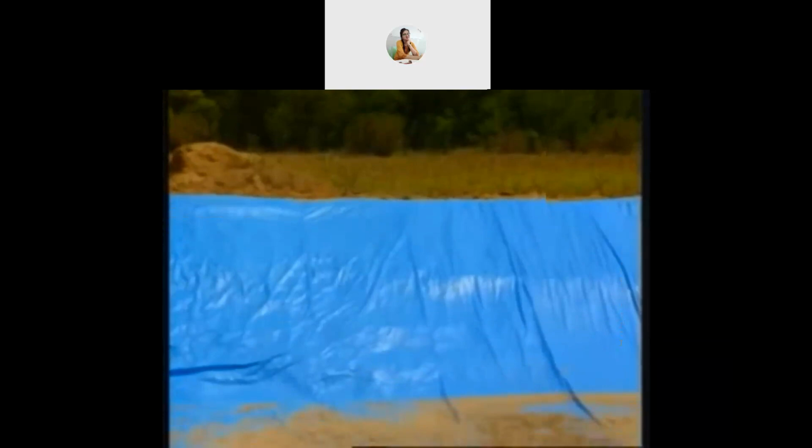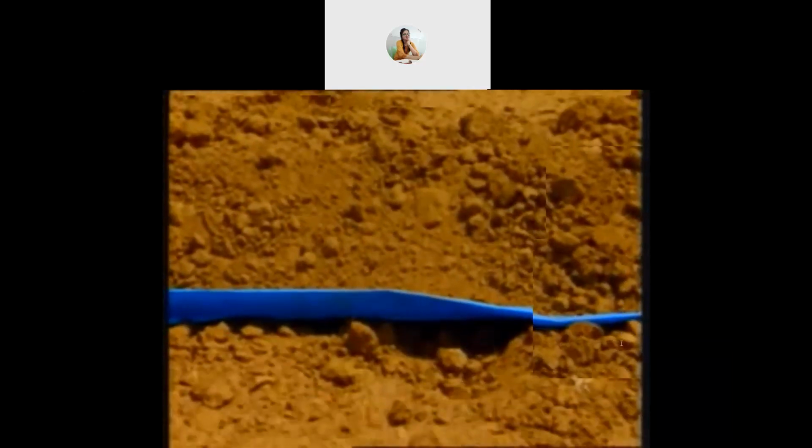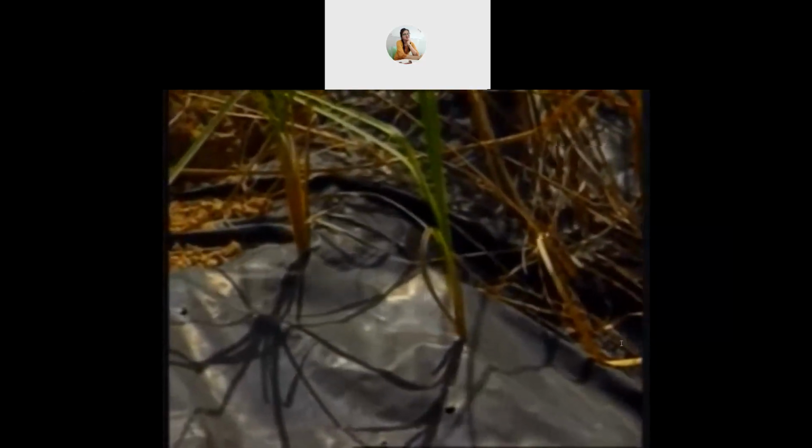Plastic film and a layer of bentonite protected by earth or gravel cover are cheap linings. These are commonly recommended linings. But the drawback in membrane linings is that they are susceptible to damage by weed roots. In this case, permissible water velocity is also limited in order to avoid erosion.